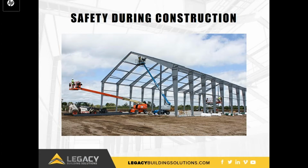Many installers working in open web trusses install the frames and then flex them one at a time during installation, leaving secondary members unattached during the installation process. If a strong gust of wind blows through while the frame is flexed, it is likely to harm the building or anyone around it.